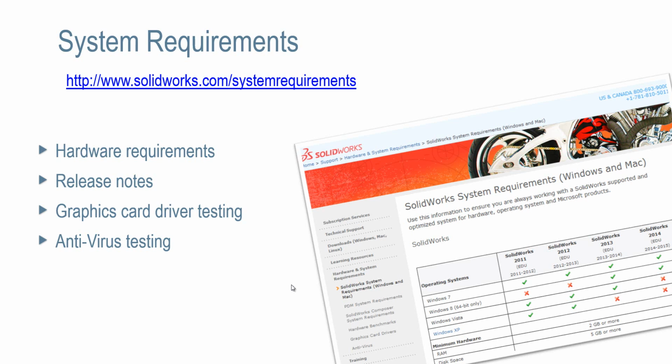If you're still using Windows 7 or Vista, for instance, it's called SolidWorks Tools in that case. Or just in the search, type SolidWorks RX. On there, there's a diagnostics page, and it will display your current driver and whether it's the right one. So there's two different ways there for graphics card testing.